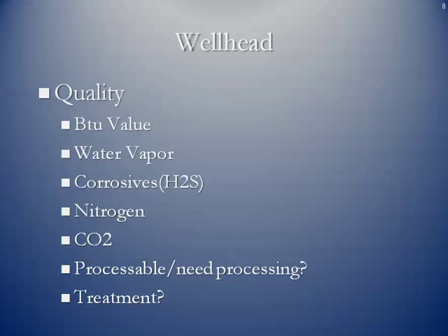Water vapor, we don't want water in the gas stream, nor do the pipelines. Any types of corrosives, there is sulfur which naturally occurs in the raw natural gas down in a well. It can actually lead to the formation of hydrogen sulfide, which is a corrosive. That is, it can eat away at the steel pipe. Nitrogen itself just takes up space. It has obviously no heating content. The same thing with CO2. Carbon dioxide just takes up space in the pipe. And so you don't want these inerts in there because you want to fill that pipeline up with as much heating content as you can.